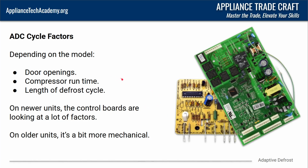So depending on the model, it's going to look at how often the door is open, how long the door is open for, the compressor runtime, and then the length of the defrost cycle. And of course, on brand new units, there might be some more factors that play into that, but we're going over the basics here. So on newer units, the control boards are looking at a lot of factors.